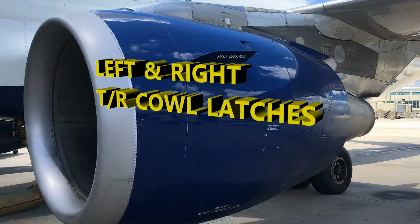And then 6 and 8 are compression arms that come in contact with the remote latches on the right thrust reverser cowl. Okay, so there's a connection between the left and the right reverser cowl latches, just so you understand. 3 and, like I said, 3 and 4 are conventional hook latches, and then L5 is a conventional hook latch. It's also unlatching the remote latch L7 with a cable. So there's your L7, which, by the way, L7 telescoping rod is connected to the 2 thrust reverser cowls.